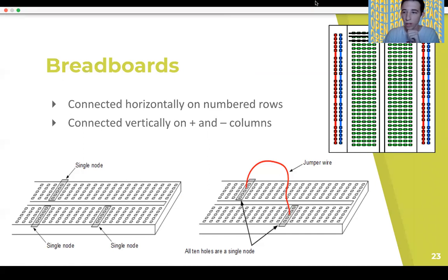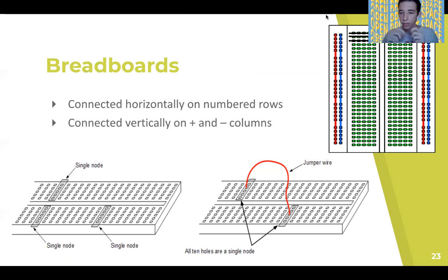All right. Now, a lot of you have breadboards in the kits you already got. So the breadboard is how we're going to make the circuit, what we're going to put it into that holds all our components together. What's important is to know how the nodes work on the circuit. So if you look in the top right, any of the points that are connected with the same color line are on the same node. On the left and right, we have these long vertical columns, and they're all on the same node. So if you connect a component to the top and bottom of the same column there, they'll be connected via wire almost. And then in the middle, we have horizontal nodes. So every row is on the same node.